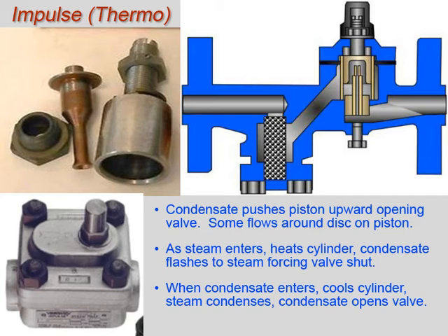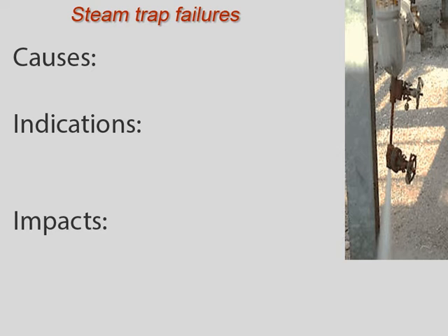If an impulse steam trap is stuck open, indicated by steam blowing out the discharge line, or stuck shut, indicated by nothing coming from the discharge line, the stethoscope can be used to check for clicking sounds to determine which trap is malfunctioning. Just like any other mechanical component, steam traps are susceptible to failures.